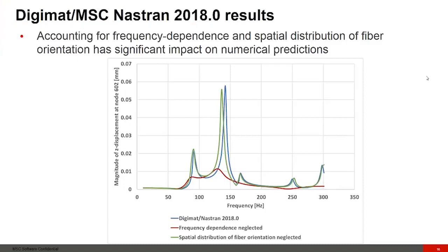One thing we noticed in our previous versions of Nastran is that depending on your rotor speed, your mode shapes may switch, and therefore for this version of 2018.0, we have added mode tracking capability and enhanced algorithms. Our mode tracking algorithms are based on orthogonality of left and right eigenvectors, but we can also do it numerically based on first and second derivative continuity.